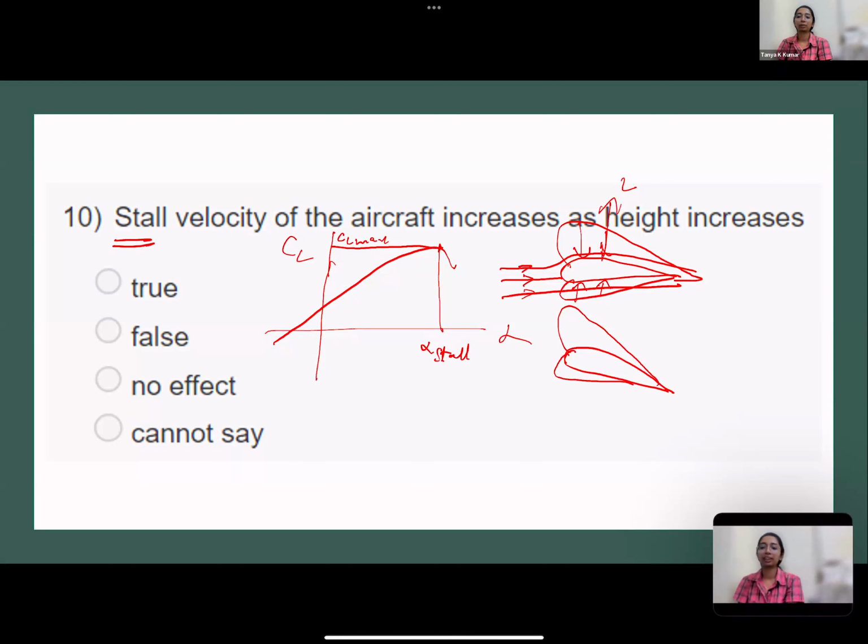Upper wing won't have much flow of air. Correct. So there is a boundary layer separation. Have you heard of this phenomenon? It's called boundary layer separation. When I increase it further, this flow of air separates at a point. So there is no sufficient lift or sufficient pressure difference, like you said. That's absolutely right. Which is why your lift generation drops beyond alpha stall.